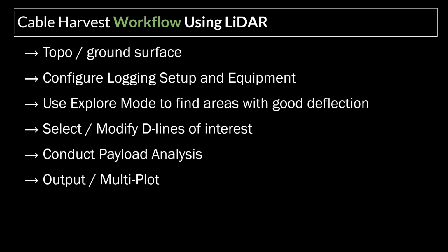This is the topo, the LiDAR service. We can talk about, create it, import it, generate the TIN. And from there, we're going to go ahead and configure our logging setup and our equipment. So they are two separate dialogues. You're going to have to input them in, but the logging systems, that's the type of cable configuration you're working with, the different cable working tensions, the carriage weight, those types of items.